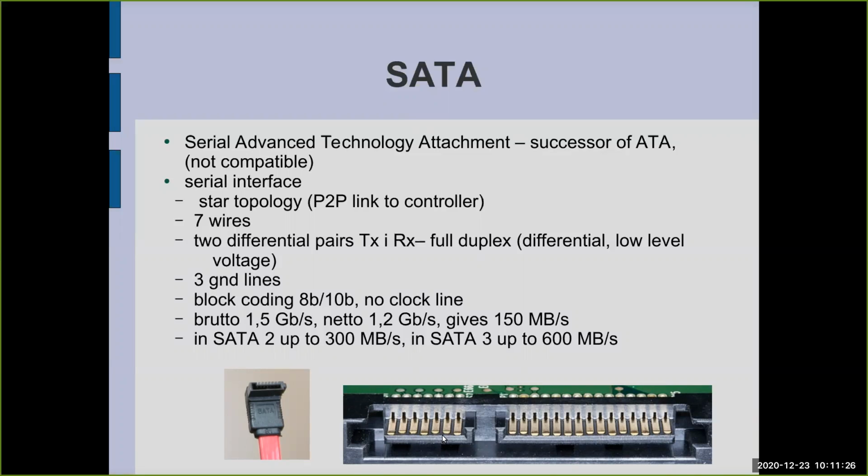So first, when we connect a device, it is a mechanical feature. When I connect the hard drive, the ground lines are connected first. So it makes the potential of both devices equal. And then after several milli or microseconds, the signal lines are connected.